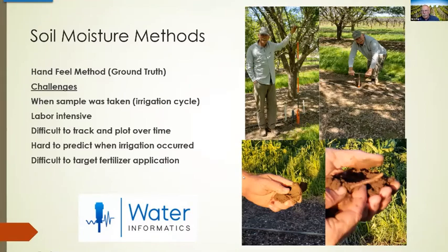So here I am. This is kind of the old school thing, and you can see me there in the top left. That probe's 6 foot long, and the orange on the bottom is the actual auger. I've got a 1 foot break, then it goes to 3 foot in that orange, 4 and 5 at the top. In the next picture, on the far right top, you can see I'm down at 5 foot. That hole took me about 45 minutes to drill, and I've got really good soil to probe into.